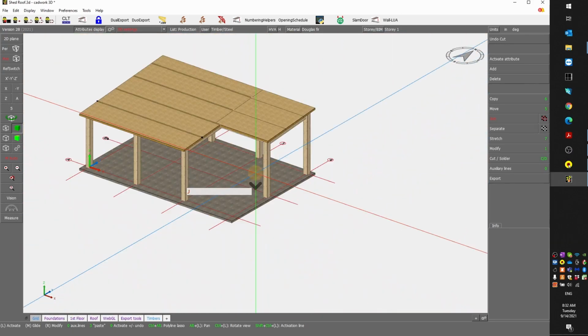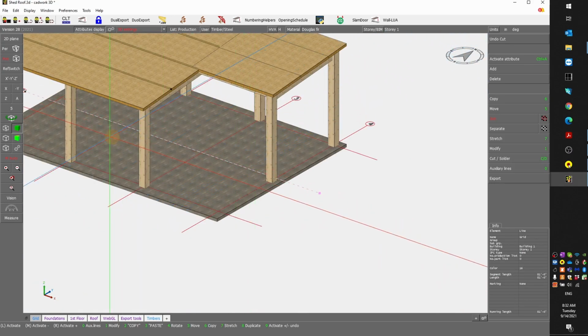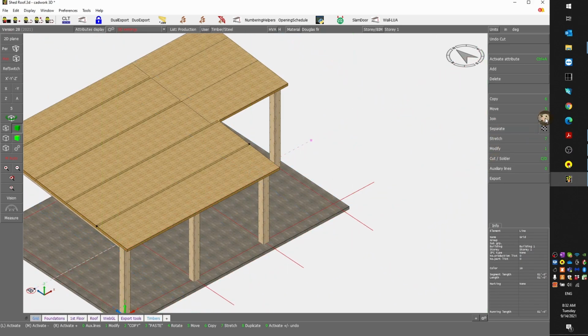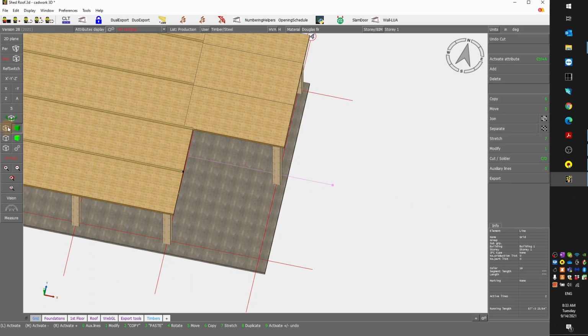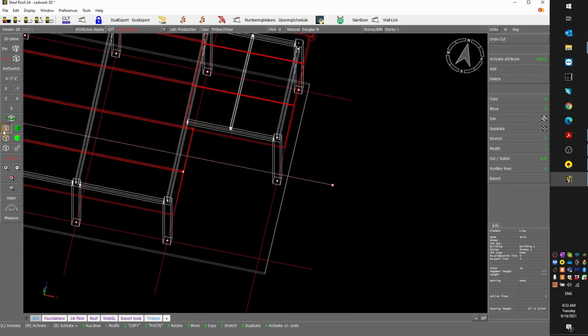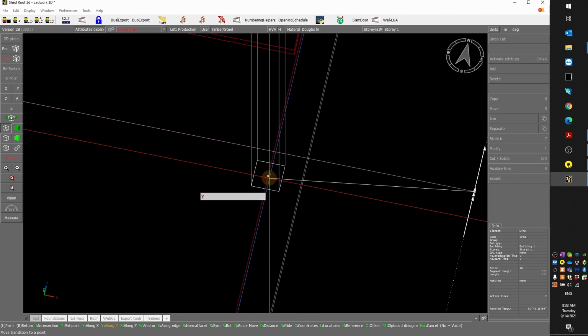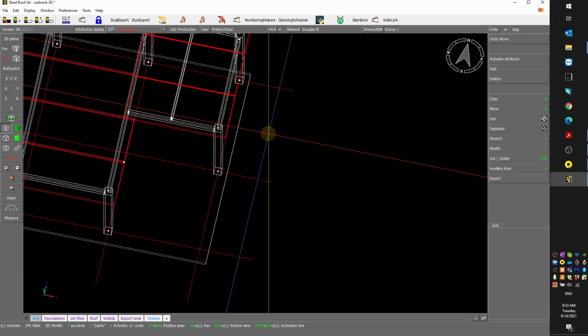So now I still need to fix my grid line, because the grid line was not placed properly there. So I move it, I go in wireframe, left click here on the left, 5 to move. We want to move in Y direction, and I pick the center here. There we go.